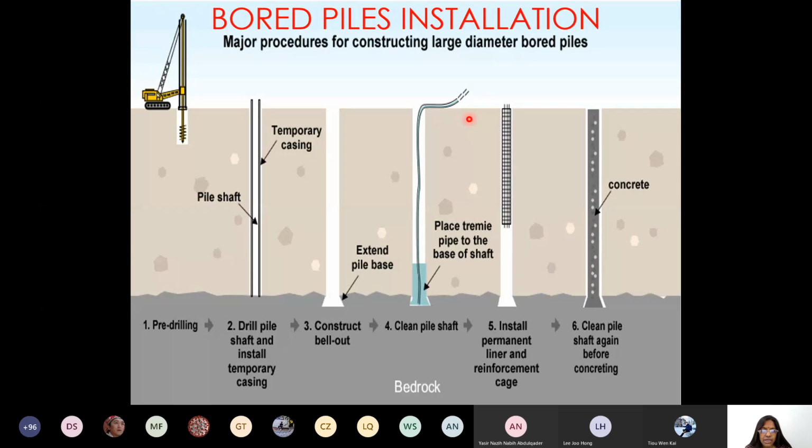Seniors, can you answer me? Did you take any module on foundation engineering? It is not foundation in engineering, which is a pre-degree program. I'm not talking about that. Foundation engineering will deal with how to design a deep foundation, how to design a shallow foundation. Design means you calculate all the types of load and properly suit the dimensions of the footing. If it is shallow, if it is pile, what is the depth, what is the diameter. If it is the reinforced one, what is the reinforcement arrangement. If it is a concrete one, which grade, which depth, right?